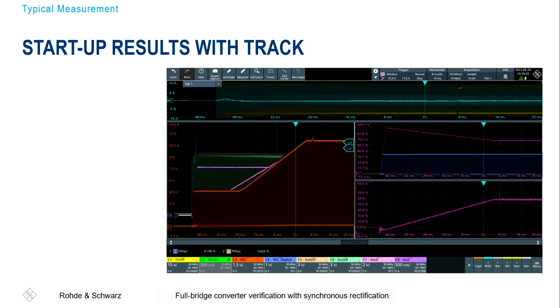But the synchronous rectifier here is quite fast, and then the duty cycle decreases, and then they enter the steady state condition. So this is, I think, not the best way to be that fast here. Also because the synchronous rectifier are not so important during the startup time. I would even avoid to use them, and then when you're in a steady state, you can switch them on.